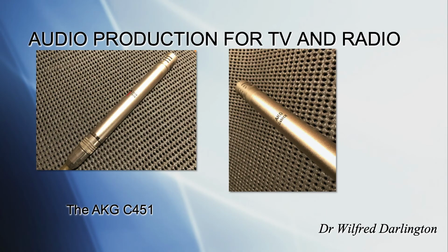But you may have been asking how all of this detail is useful to the practical sound technician. Well, there is a lot more to say in terms of the practical application of microphones. Conventional capacitor mics have direct voltage sitting on the capsule of the microphone. In damp conditions, this voltage can leak in moisture droplets across the plates of the capacitor.